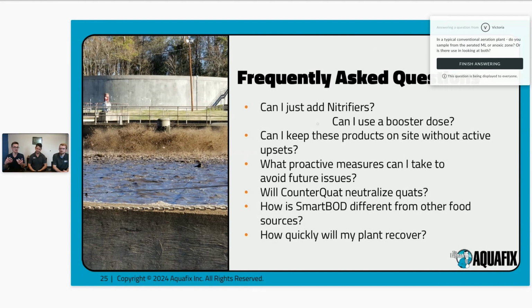That's going to be most likely your aeration basin, where it's being aerated and mixed the most. That's where a bulk of your treatment is taking place. So that's what we want to focus on. And that's going to tell you a heck of a lot about your system.